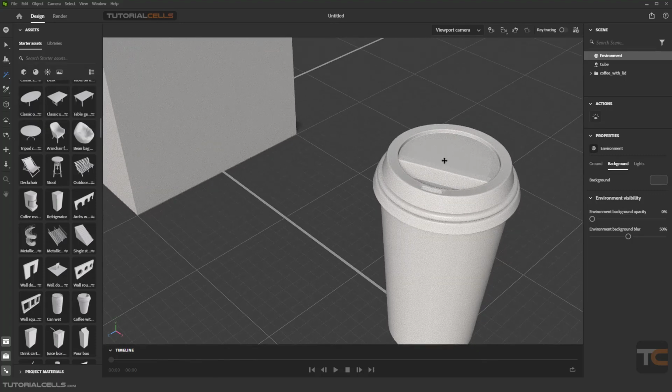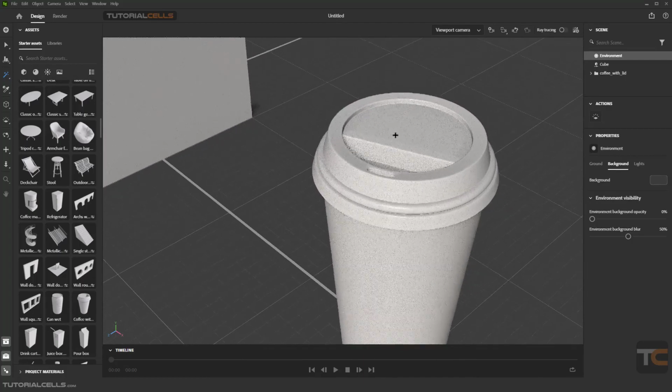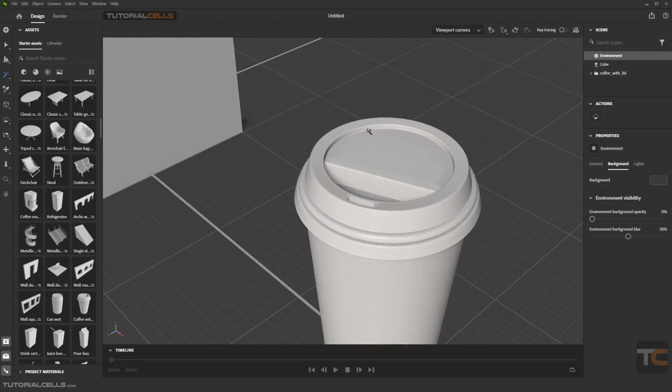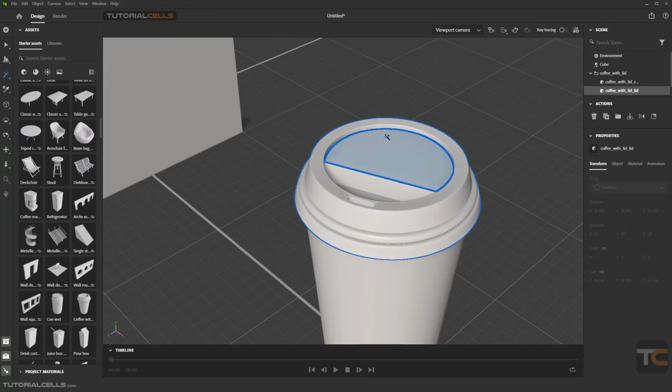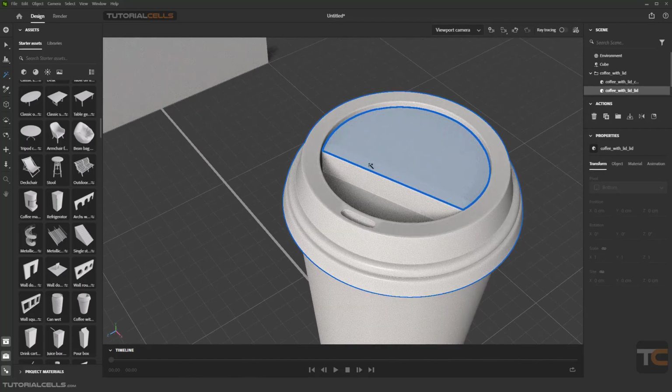For example, in this, you can choose different polygon surfaces depending on the edges from this lead. Okay, let's select that and then just click. Now, as you can see, it selects that polygon, that surface of polygon of this lead. And then you can create a different material for that, or hold shift to add.